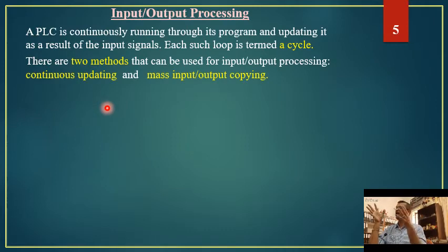So if we have something like, say, 1000 sensors that are connected to a PLC, then the first sensor is sending an input, then the PLC will first of all engage itself with that particular signal that is coming in, and then it finishes off that one cycle with that particular sensor. Then it goes to the second sensor, and the second sensor is sending some input, and that particular input is identified by the PLC, and one more cycle is being run.